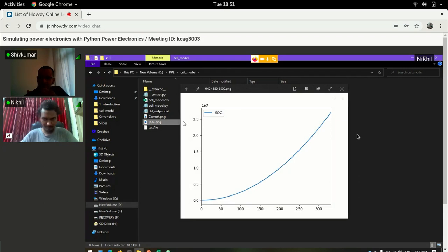So the first thing we have to note is, one, we must cap our SOC, right? Because we must cap our SOC at a certain value, because once our battery is fully charged, SOC cannot increase any further. It is at 100%, right? So the first thing you must determine is what will be your max SOC. That is 1 per unit, but this is not per unit. So 100. Again, or maybe the capacity value. So, exactly. Okay. So 2.5.